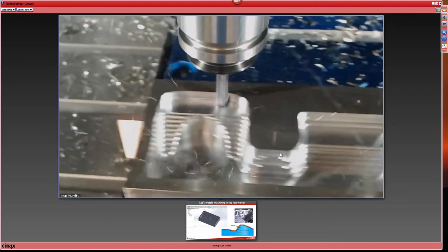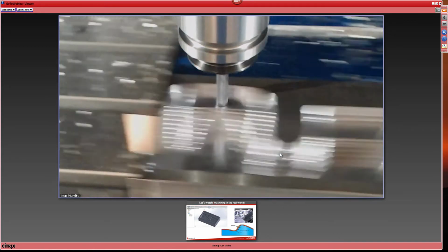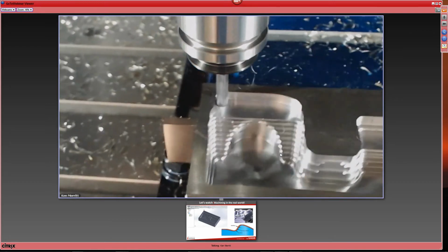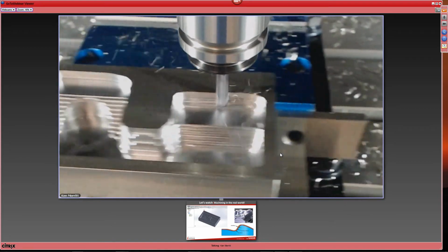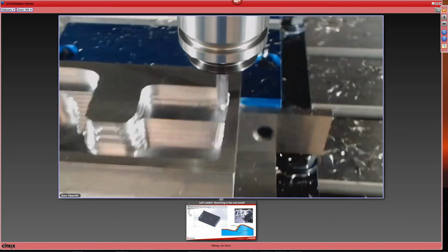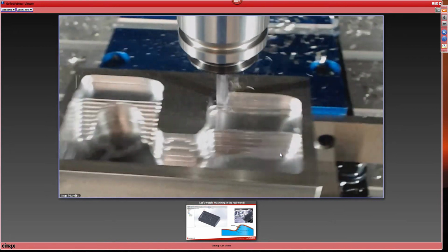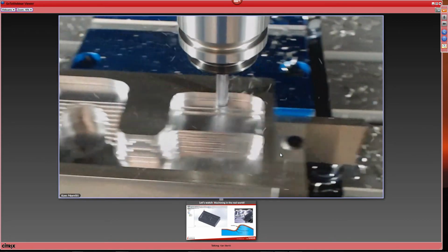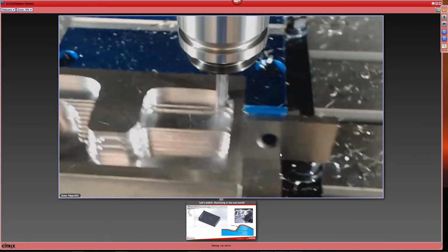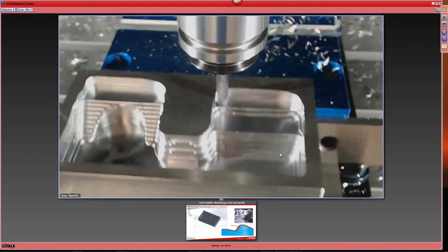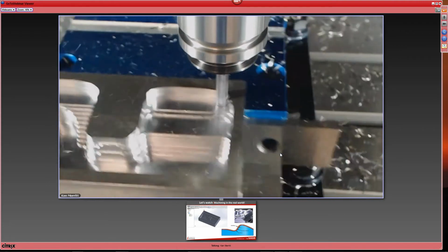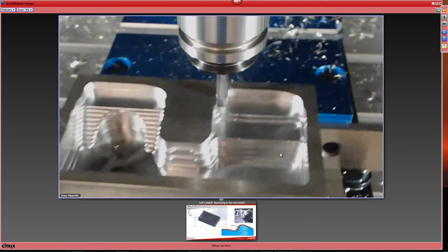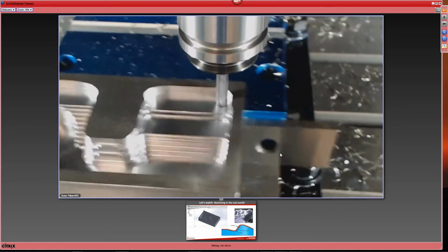Now you're going to see today, I'm going to go straight from this roughing operation directly into finishing toolpaths, and we're going to result with a very nice surface finish without having to waste the time to do that semi-finished cut. So not only is iMachining very, very fast and removes a lot of material very quickly, but in many cases it can basically obsolete an entire semi-finished pass. Think of how much cycle time that's going to save you on each part.